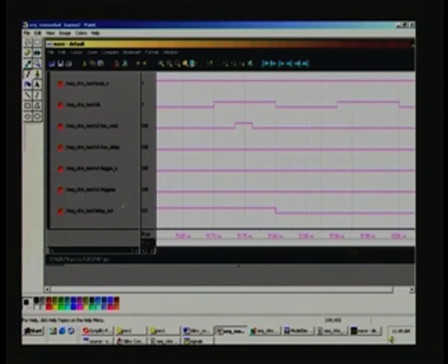So, after all, delay out is dependent upon, to start with, when it is switched on it may have one particular delay, it may have to go through a set of gates, and when it is switched off it may have to go through another set of conditions. So, that means another set of gates is coming into the picture. So, between these two sets whatever is the propagation delay difference will manifest as the error. And that is what you have here, 3 nanoseconds explained. Is it clear? So, this completes the back annotation.